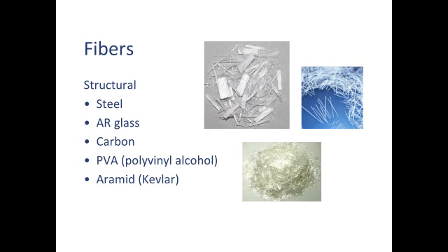The ones we use are glass fibers and the PVA fibers. PVA fibers are really cool because they're synthetic fibers that are finer than a human hair, or the ones we tend to use. And the cement paste bonds to them really well. They're used for microcrack control. Because they're so fine, it's easy to overdose them, and when you start to use too many PVA fibers, you can actually end up with concrete that's weaker than it would have been if you hadn't used PVA fibers. So it's very important to use the right dose. They can lead to hairy surfaces, hairy concrete, because they can stick up a little bit, although a blowtorch or just sanding them off makes it go away very easily.